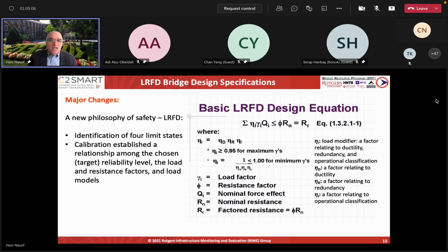How do we get those? And then from the resistance side, you have the same thing. You ask for Fy of steel of 60, and maybe 98% of the time you get it above 60. But there will be times when you get it a little bit lower than 60. Although now there's good control of the quality, the statistics of what we are getting show that there are some samples that will be below the target values, right? So there is uncertainty there.